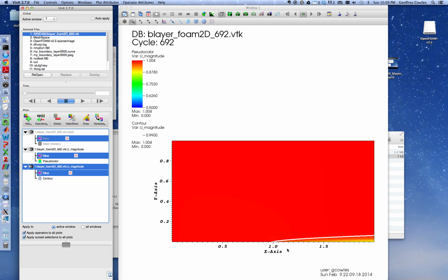So you can kind of see how it grows. This is the square root of x. This is a laminar boundary layer, and the thickness of it grows with the square root of x. This looks just like a square root function here. And it's actually fairly thick by the end of the plate. At this low Reynolds number, we have a fairly thick boundary layer.